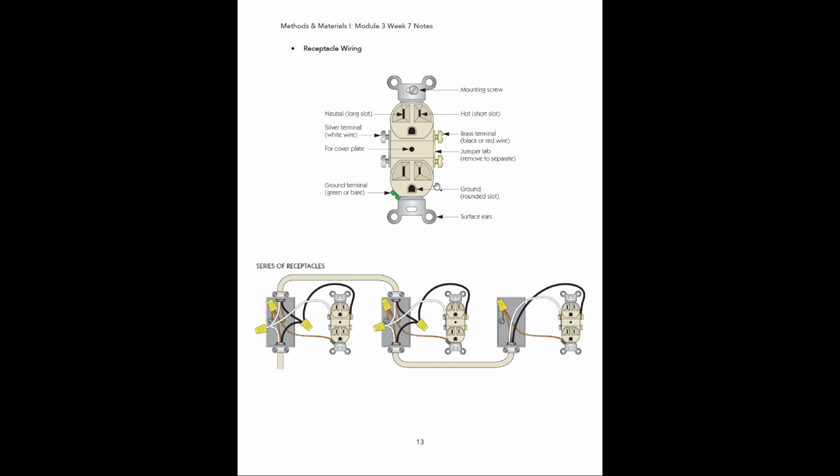Okay, so if you live in an older house, or if you've ever seen an outlet that does not have these slots at the bottom, those little D-shaped slots, that means that outlet does not have grounding as a part of it. So if something like an accident were to happen, that outlet would not be protecting you, because there's no grounding functionality built into it. Anytime you see that little D-shaped hole at the bottom of the plug, you know that it is a grounded outlet.